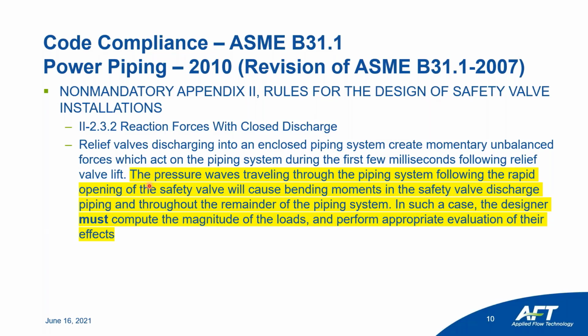The pressure waves traveling through the piping system following the rapid opening of a safety valve will cause bending moments in the safety valve discharge piping and throughout the remainder of the piping system.